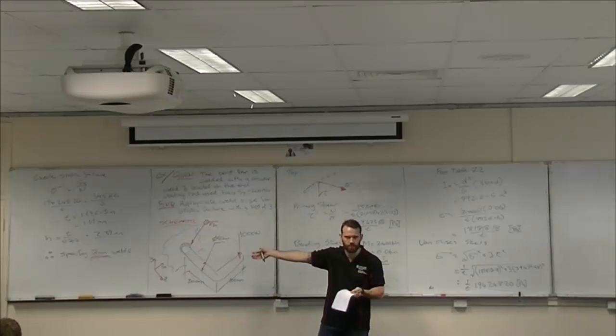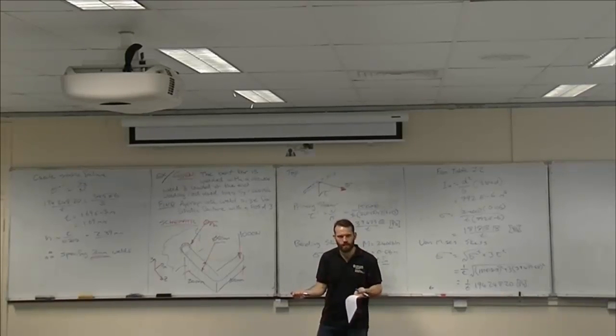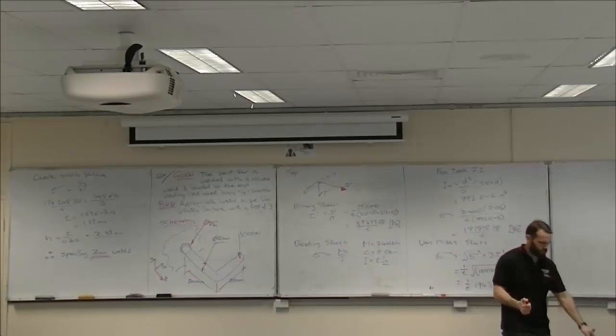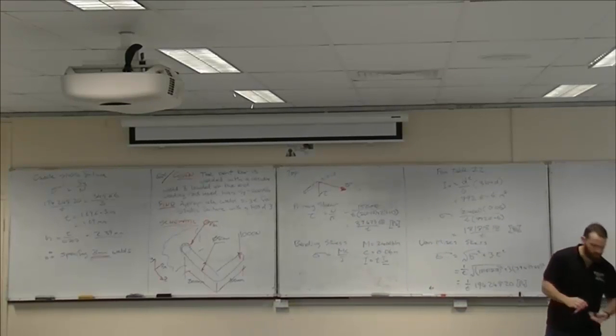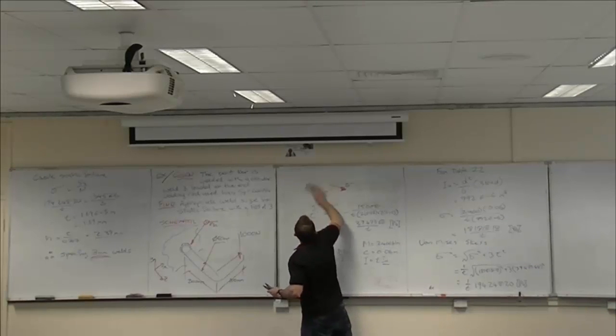Where's our bending maximum? Top and bottom. So already we can look at it and with our good engineering eyes work out which is our critical element to analyse. Work out the primary shear, the secondary shear, the bending stress, what's the von Mises stress, and then compare it to the failure criteria. Easy enough? Go. And I'll put the 1/6 equation up for you just here when you get to it, just in case you didn't copy it down quick enough.